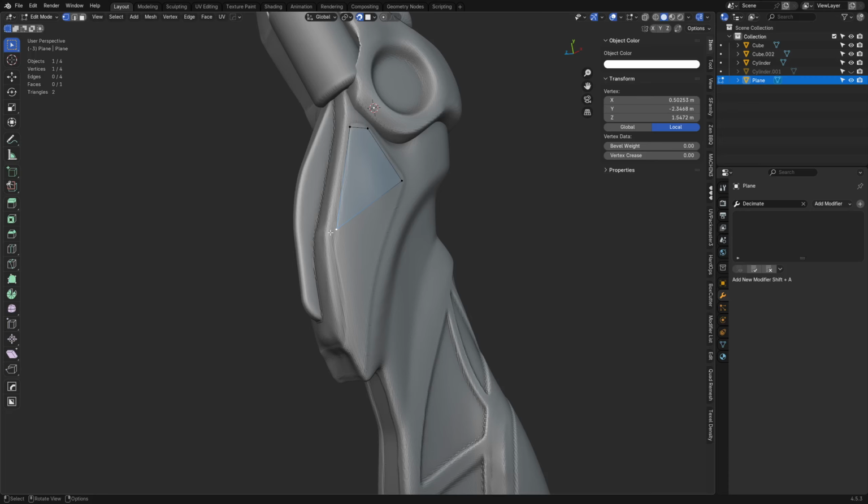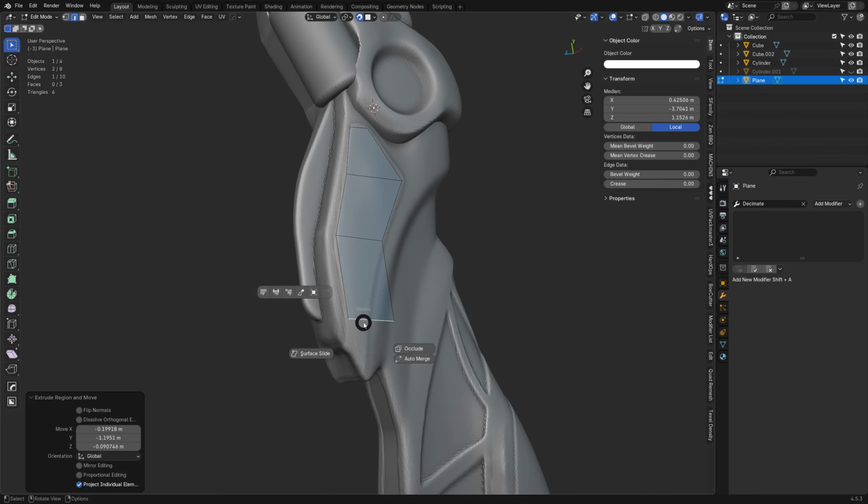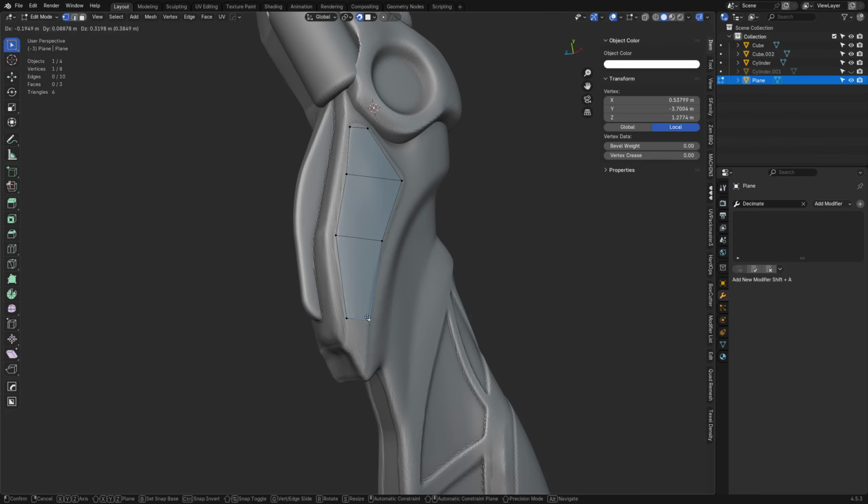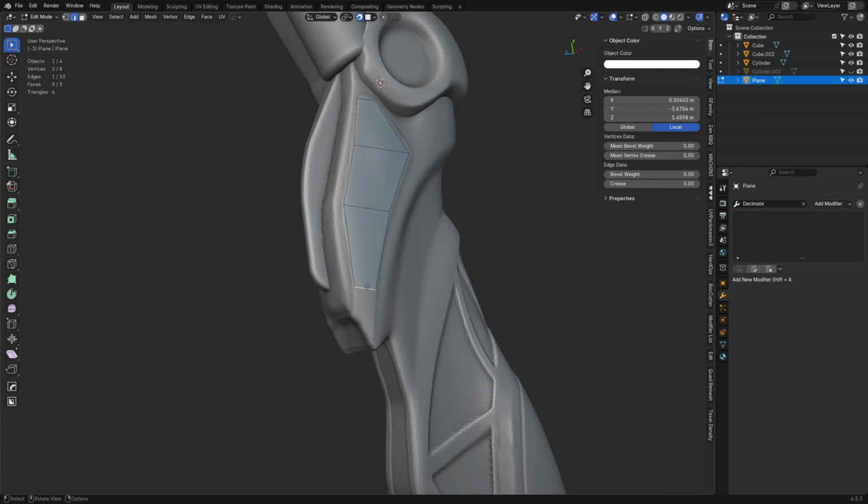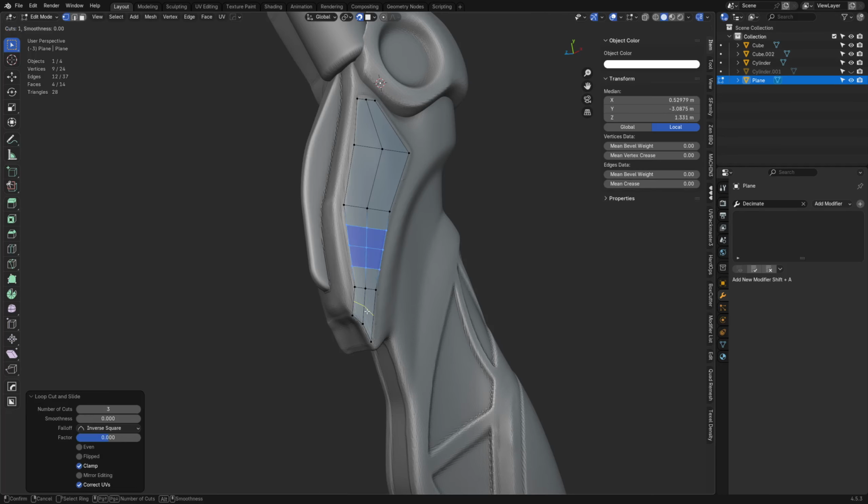I wouldn't use shrink wrap, and I wouldn't do that for one reason: the problem with shrink wrap is it picks up a lot of the errors or little small discrepancies you have all over the surface of this thing, and that's not really what you want. You want to create really nice clean quad topo. Use creases if you want to sculpt on it again with multi-res or something like that, and keep them as quads basically.